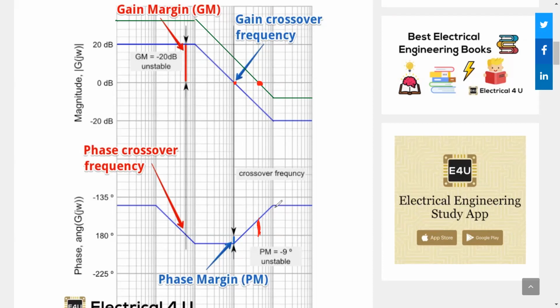So the direction in which phase margin points changed. And that means, interestingly enough, that somewhere while we shifted, it went through 180. So what I'm trying to say is that with Bode, you need to be careful about how you analyze those margins.